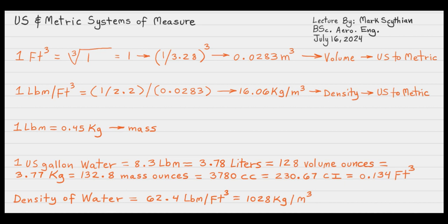Again, we could take the pound per cubic foot, let's say air density, and convert it to a kilogram per cubic meter value. So air density tends to be like 0.074 pounds per cubic foot at standard conditions, like 60 degrees Fahrenheit, near or at sea level. But imagine a whole pound per cubic foot. That's a pretty heavy gas. So it would be a very heavy gas, or could just be a 1 pound per cubic foot metric. It'd just be a conversion factor metric, right?